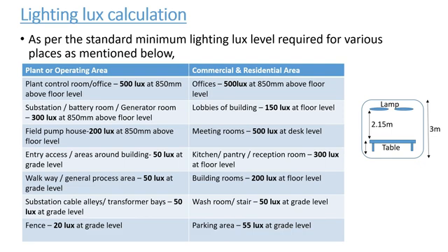and areas. Suppose you are going to do the lighting system for a process or operating area, or a commercial and residential building, so they give two different standards. Based on that you have to select. For example, for the process or plant area, I'm going to do the lighting system for a control room or office in the plant. There that room requires a lighting brightness of 500 lux at 850 mm above floor level. It means you can see here, for example, this is one room.